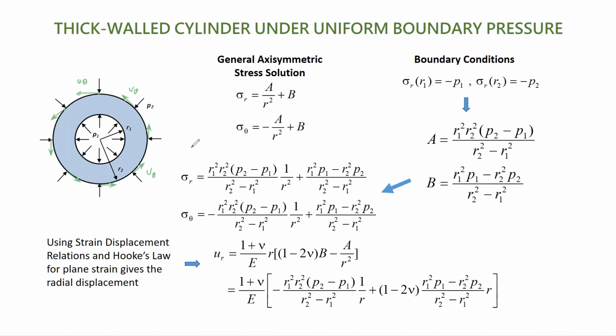What does it reflect? It seems that if you do that sort of displacement, every point is rotated by some angle. And that would be just like I am rotating this cylinder about its center by a certain angle. And that does not produce any stress or any strain in the system. That is just simply a rigid body motion.